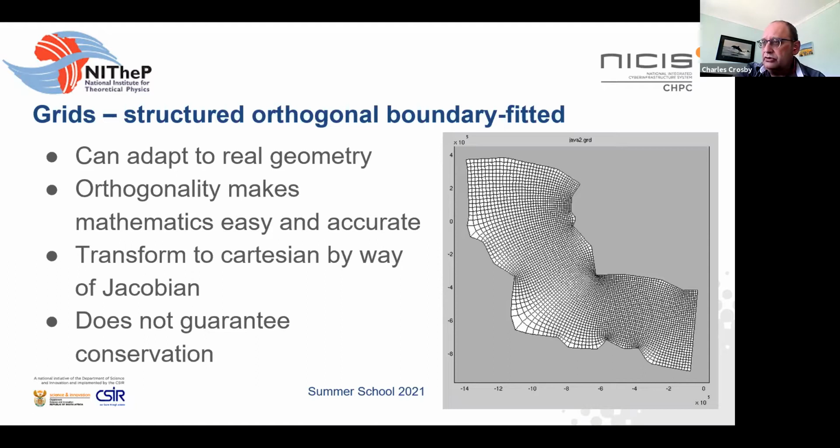When it comes to getting good quality results in CFD, one of the things that you learn quite early on is it's useful if you can keep your flow aligned with your grid lines. It means you've got minimal flow crossing grid lines, which makes your fluxes for your differencing schemes more accurate.